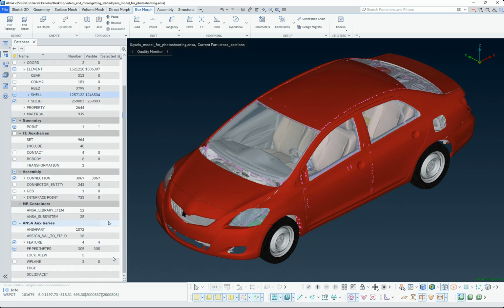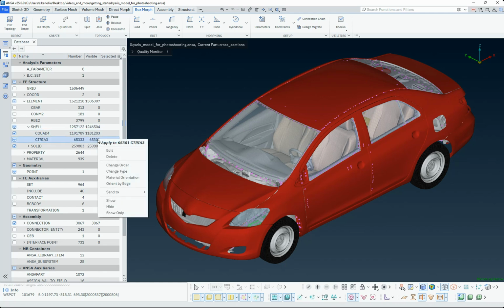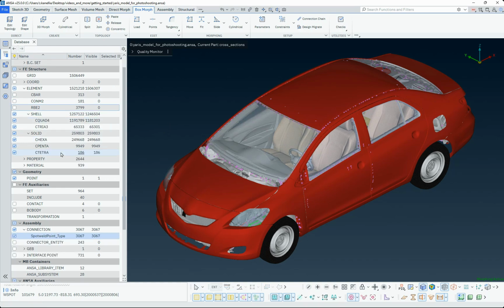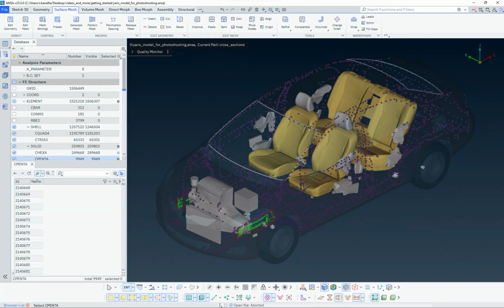Accessing functionality is done through right-click options on each entity. Direct access to the full functionality is also available while hovering on the display area. The database browser can also be used to navigate through model entities on a single entity basis through the selection lists. With the selection lists, the user can select entities for the creation of a set or include, identify visually entities that are otherwise marked, or, the other way round, select entities from the drawing area to identify them in a list.